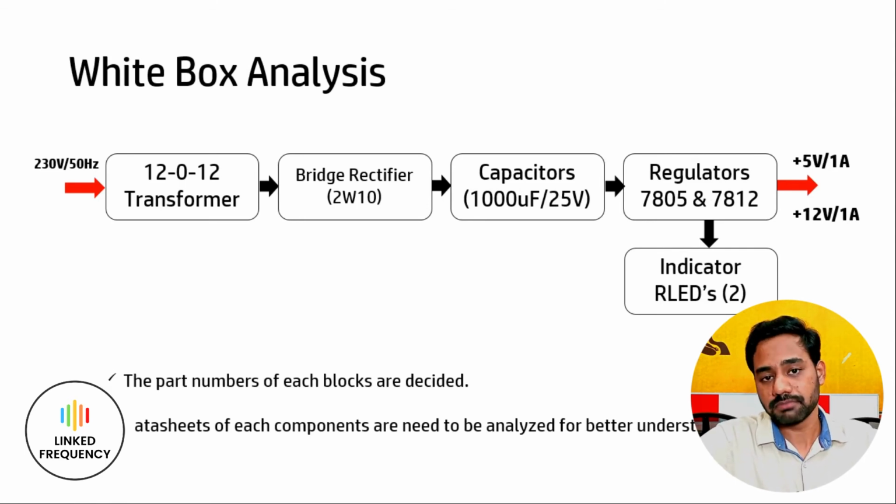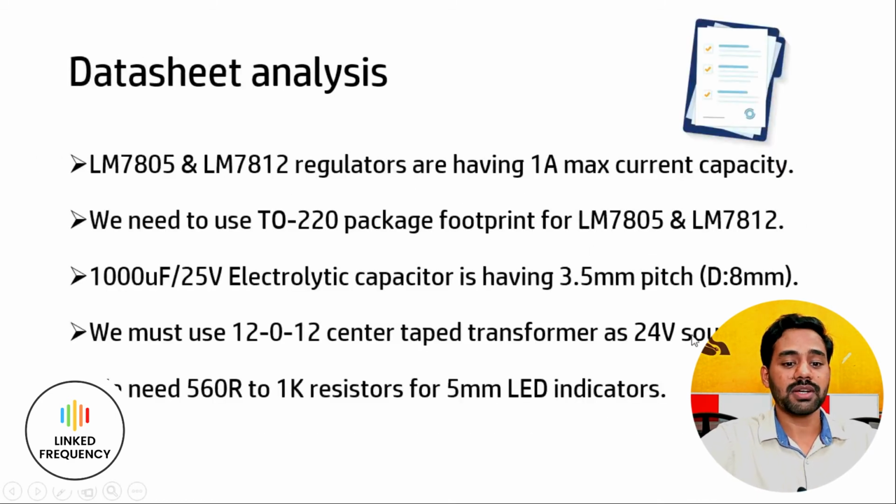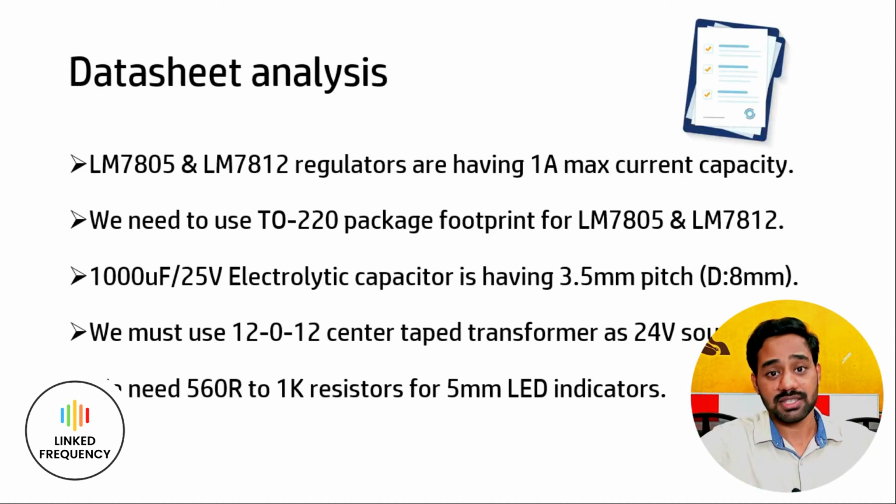That's why it is a regulator, converting higher voltages into lower voltage. In that case, it will be reduced to 10 volt or less than 10 volt if you are giving 12 volt here. That's why we must have a greater than 15 volt source at the input, so that you can expect the 12 volt DC at the output of this entire system.